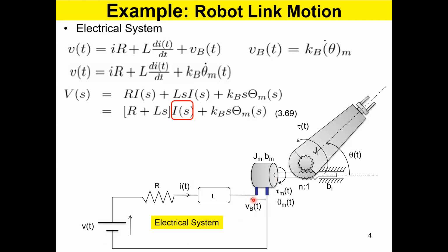Therefore it will be increasingly difficult to further speed up the motor, because the remaining voltage between these two is diminishing. That is why these kinds of typical motors, when you give a voltage, attain some speed and then not beyond that.